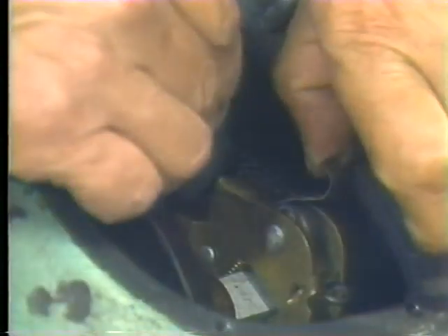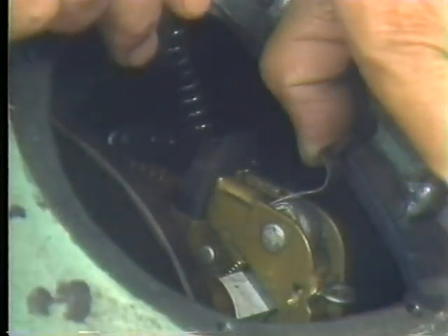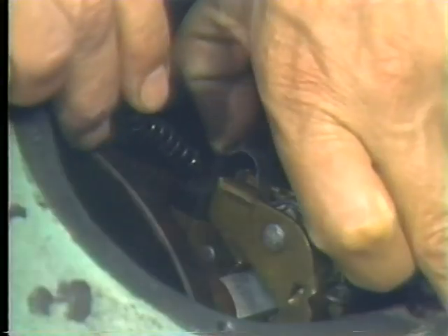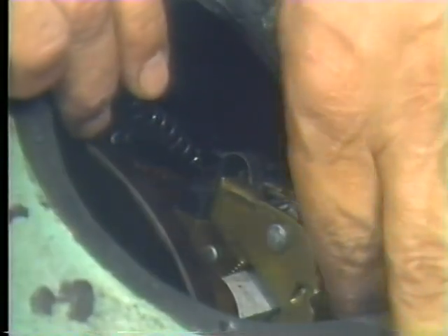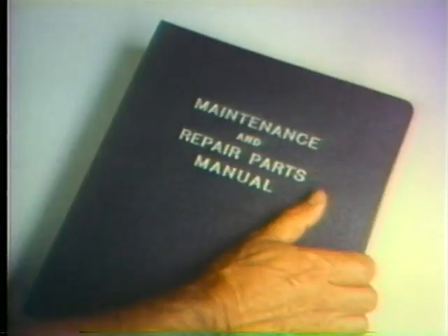Your motor is clean, and you can begin to reinstall the brushes. Start by moving the brushes up and down in the holder to make sure they're not hung up somewhere. Then set the tension devices. If there's no pressure setting given in the manual, well, a good rule of thumb is 1 1/2 to 2 pounds pressure per square inch of brush seating surface.